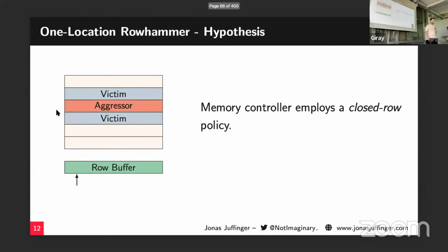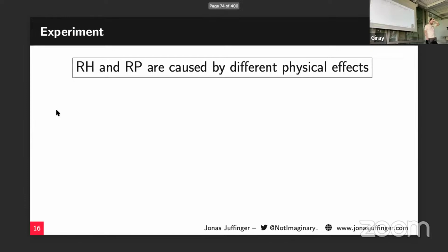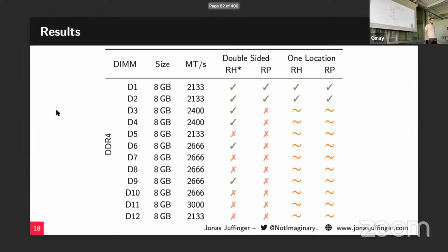So here we only access this offset because this is what we did 5 years ago. We only access the first offset in the row. And for RowPress, what they did is they accessed multiple offsets in the row. So this is the only difference. And this is why we thought it shouldn't make a difference. It should be the same result, like the same number of bit flips, same locations, because of our understanding of how the DRAM works. This shouldn't make a difference, but it did. And yeah, the sad thing is we don't really know why. It's pretty inconclusive, the result.